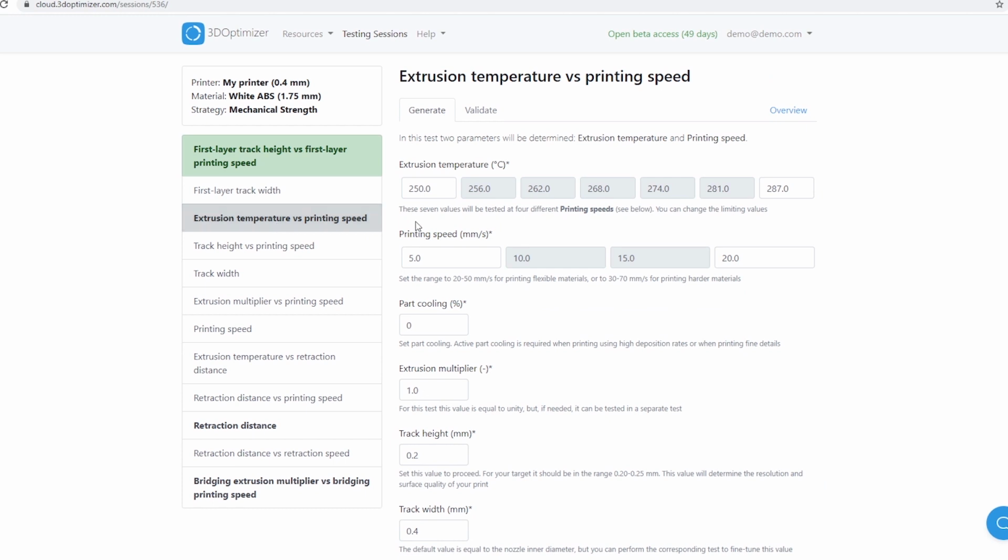That's because since I printed with 0.4mm track width and found a valid test structure, there is no real reason to change it. If I had found gaps between tracks or just had not found any good tiles to choose from, I would need to do that test as well.